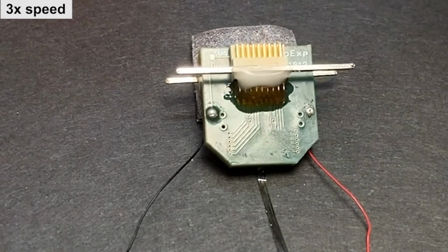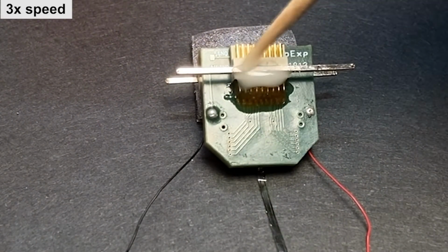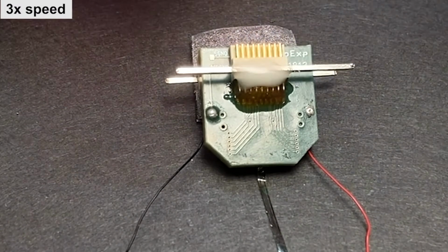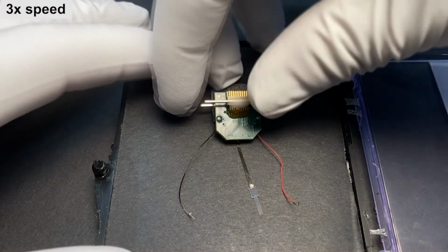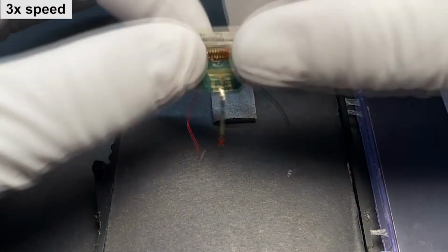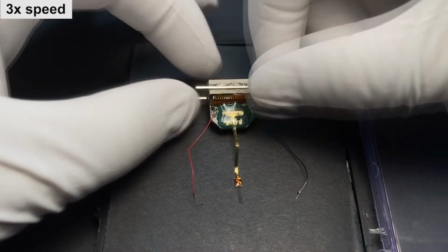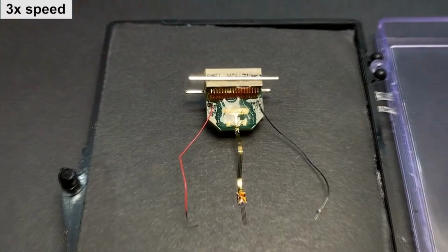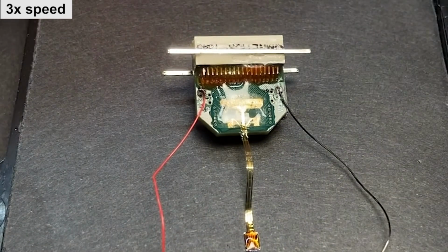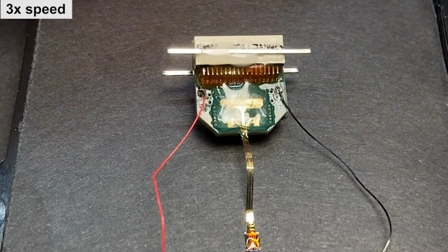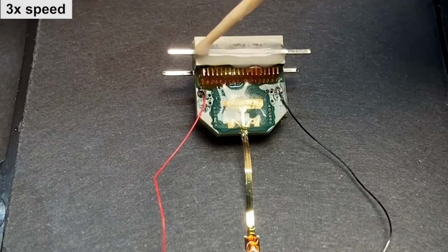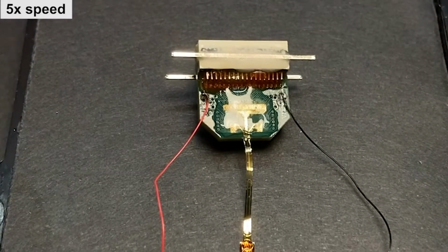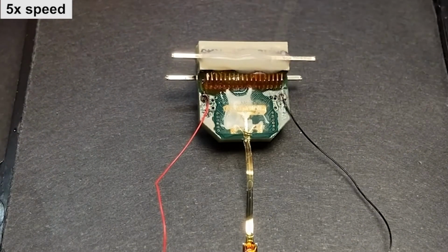connection. And this dental cement should be liquid enough to flow between the plastic and the metal, but not too liquid when you apply it here to flow to your Omnetics connectors. So during the workshop, there were some participants that basically blocked the Omnetics connectors. If it happens, it can be removed. It just takes time, and it's better to avoid it. And then you flip the probe again, and then you apply cement on the other side